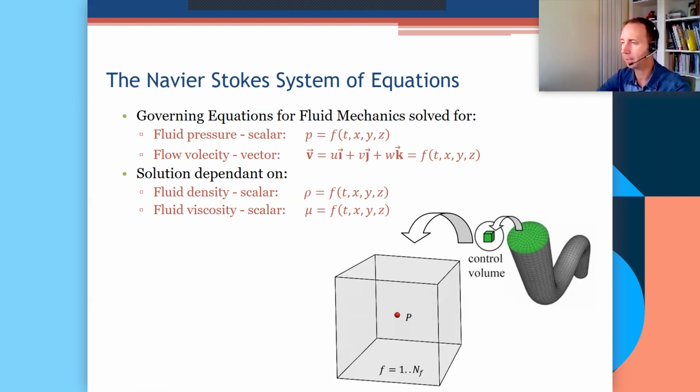It's essentially the discretization of space. In fluid mechanics, there is a method of solving for the governing equations using what we call the control volume analysis approach, which means we solve the governing equations on average over the control volume. And that's the foundation of computational fluid dynamics. Very often we start from control volume analysis. We talked about it in second year, and we'll revisit that now because it's the easiest way to explain how the governing equations of fluid mechanics are derived.